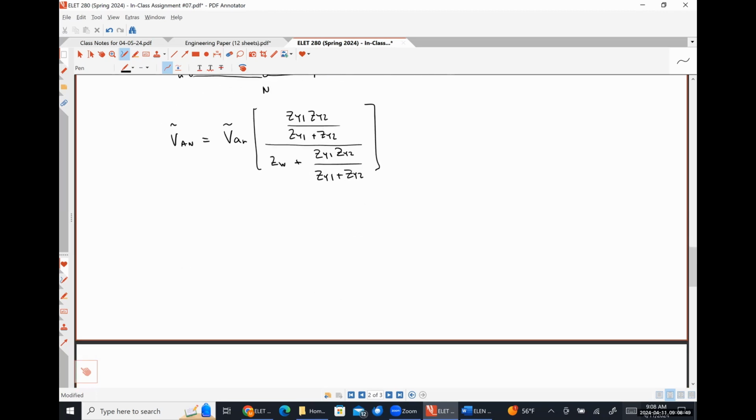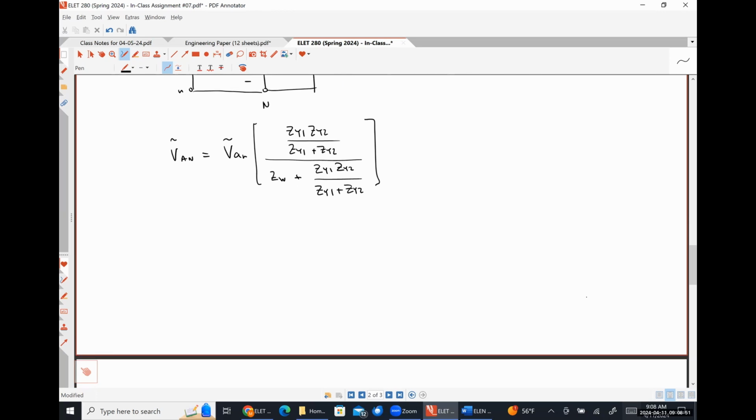Yeah, so I'm not doubting that you understand it, but just to be clear, effectively what we have is this circuit, and we're just trying to find the voltage drop across that one impedance, which to me, anytime I have a voltage source in series with impedances, screams use voltage division. Again, purely because I'm lazy and I want to get there without having to think too much. Nothing, like I said, remotely incorrect about the methods that you guys suggested, just a little less efficient.